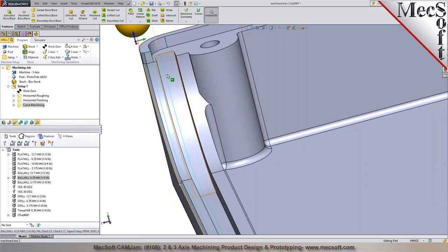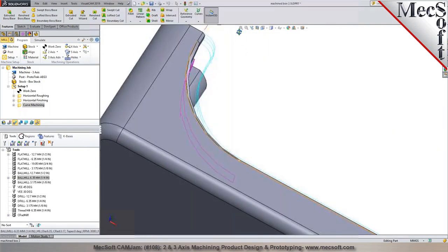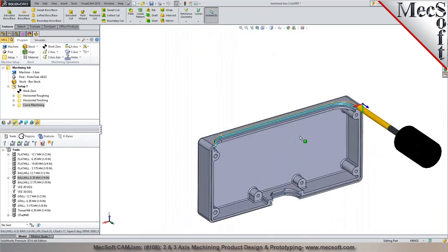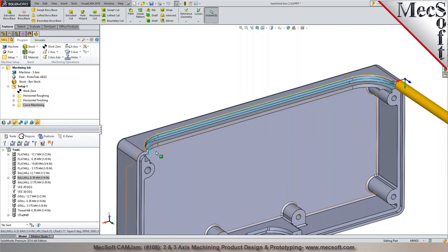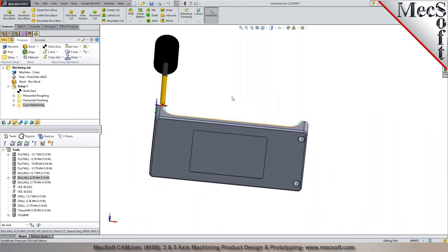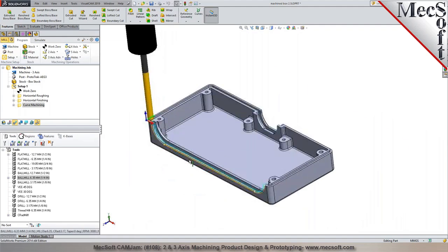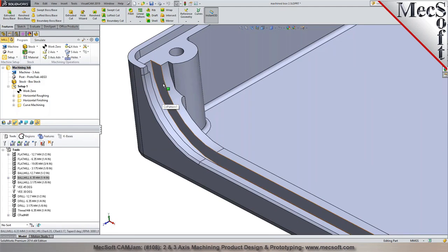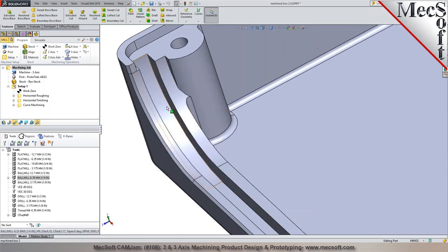And now for cutting the inside over here, you have an undercut, right? If you look at it from the side, you probably would be able to use a keyway cutter to mill it from the side. But if you just want to do it from one setup, looking down from the top, then we could use a method called curve machining. But then I'm going to just have to draw some sketch in here.